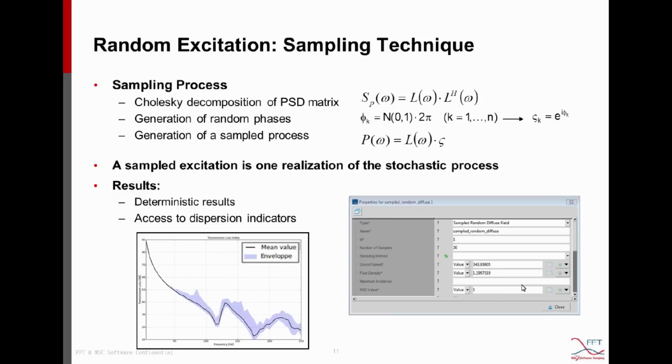In the direct frequency response, applying that matrix directly as excitation is computationally cost prohibitive. So we will find other ways to introduce this PSD excitation to the surface.